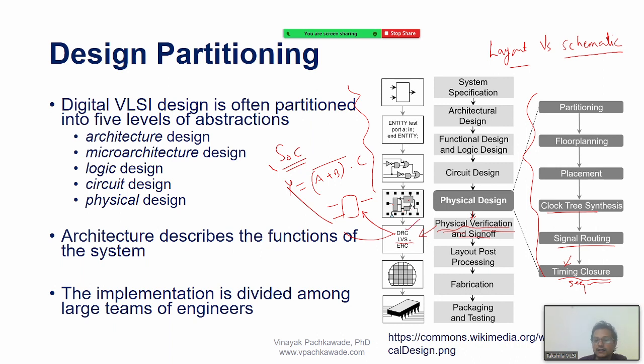So DRC is design rule check. LVS is layout versus schematic. And ERC, what is ERC? Electrical rule check. So all these things are there. Electrical rule checks means they will see where your ohmic drop and short circuits are, and all those things. IR analysis, right?